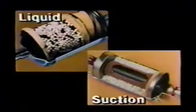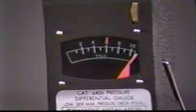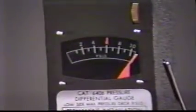The reason they are not interchangeable is the same reason their constructions are different: pressure drop. While pressure drop is important in the liquid line, it is critical in the suction line. Every extra pound of pressure drop in the suction line can rob the system of needed capacity, and for that reason should never exceed recommended limits. Limits that are very low compared to the liquid line. It is very common to change out suction line filter dryers because they have done their job well and their pressure drop has become too high.